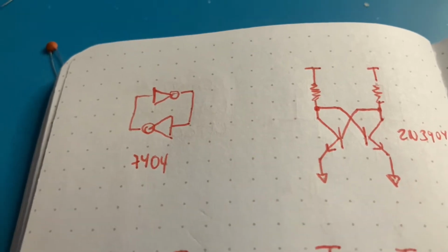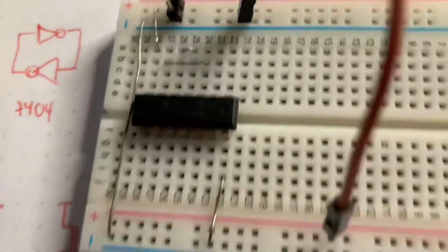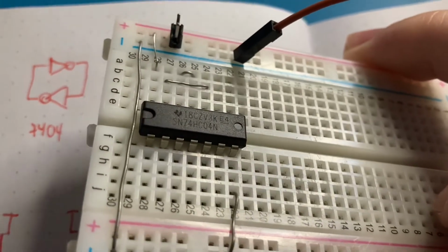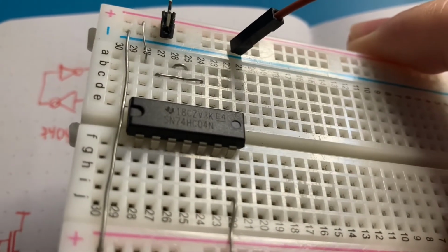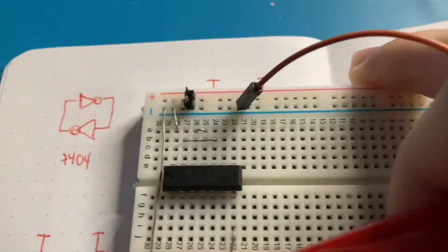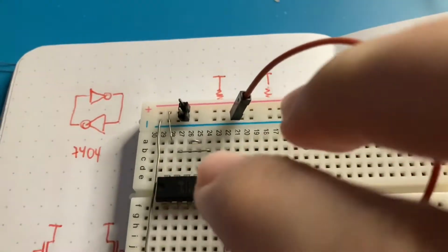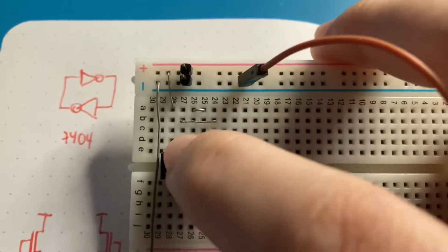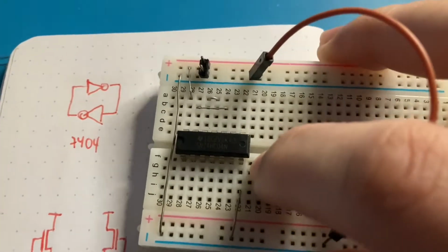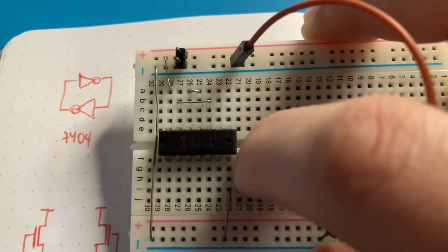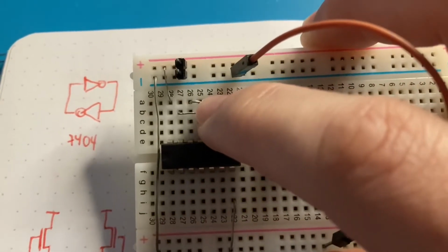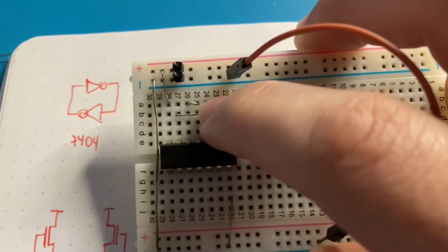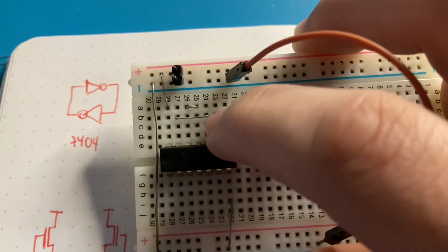For instance, with a 7404 like this, you'll not be able to see. Oh, maybe you can see, yes. It's a classic 7404, and I don't want to show my oscilloscope here or any blinking lights, but this is essentially VCC and ground, just like the datasheet asks, and then I just connect the output of the first to the input of the second gate and vice versa.